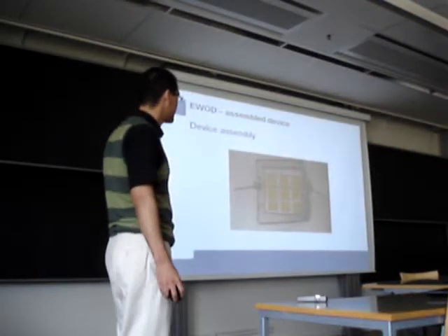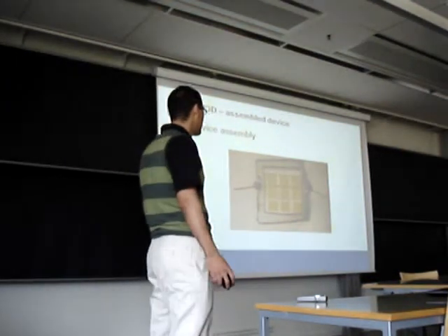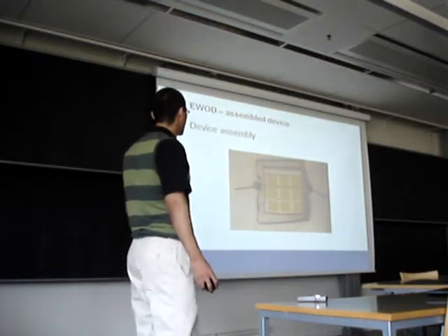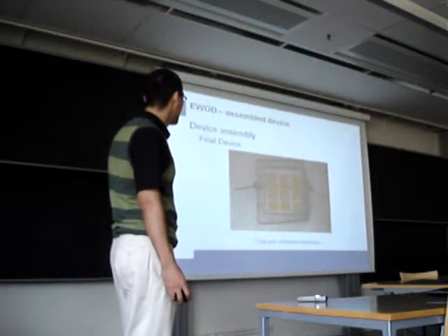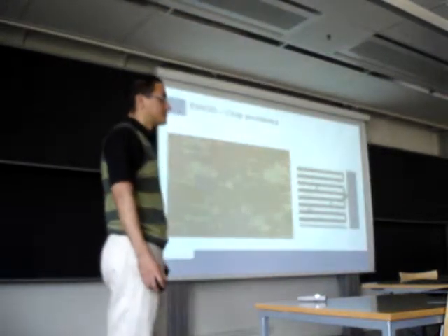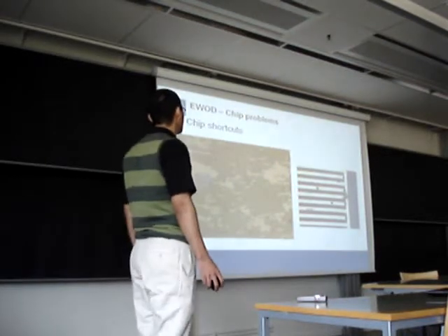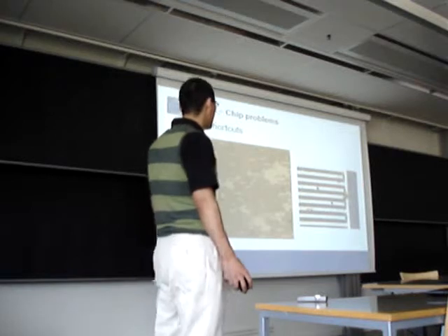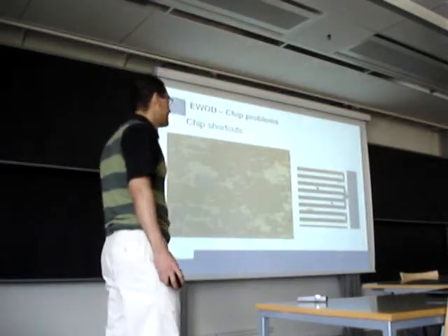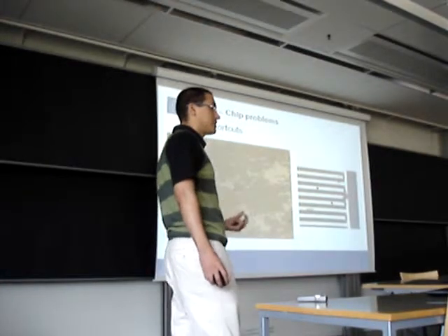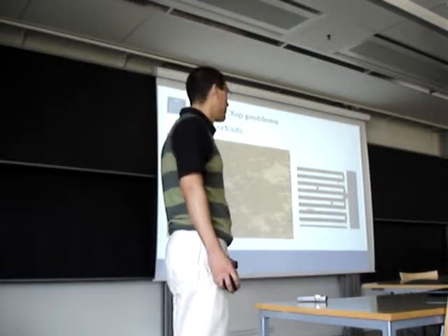I put some electrodes with solder on the sides for practical purposes also. But I found a lot of errors in the fabrication process. There were some shortcuts and open circuits, as you can see on the right, and there was a lot of dust of gold particles from the etching part. That was also a problem I found.